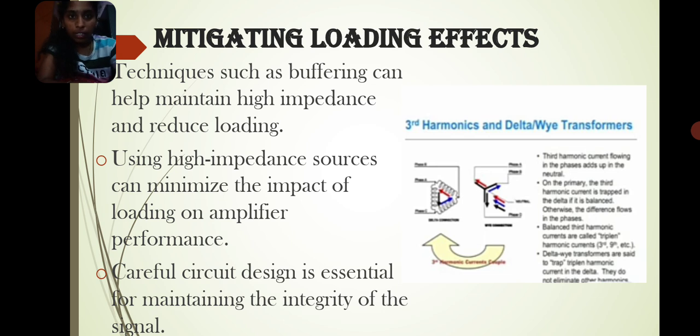Mitigating loading effects. Techniques such as buffering can help maintain high impedance and reduce loading. Using high impedance sources can minimize the impact of loading on amplifier performance. Careful circuit design is essential for maintaining the integrity of the signal.